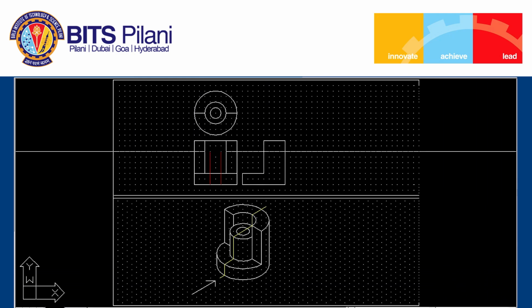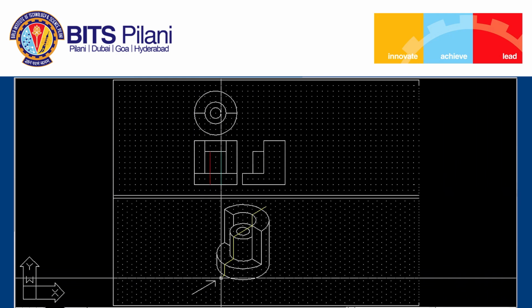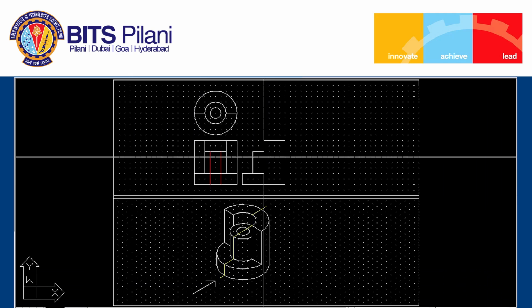Height I can get from here, 1, 2 grid space, and it will be till here, because the object is a single piece. The important thing to note now, for this principal surface, half part is visible, half part is going inside 2 grid space, that we have to show with the hidden line.